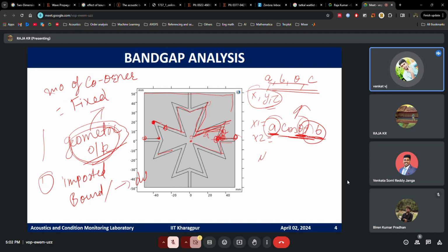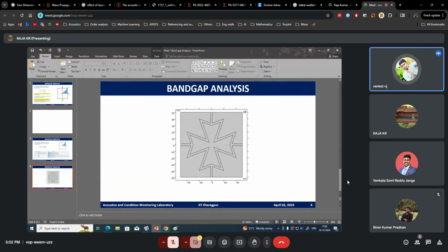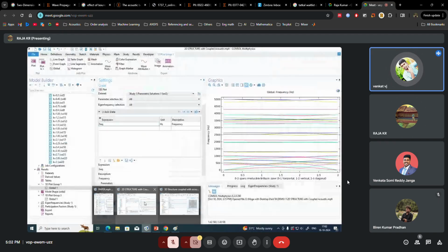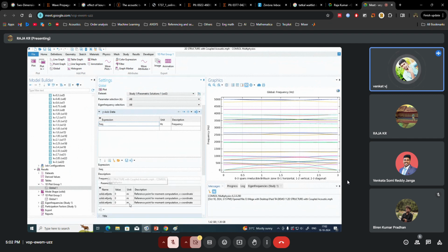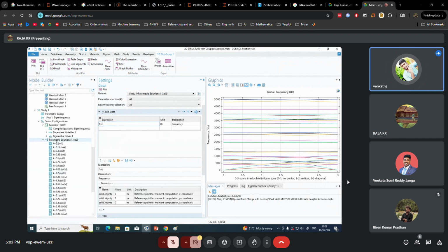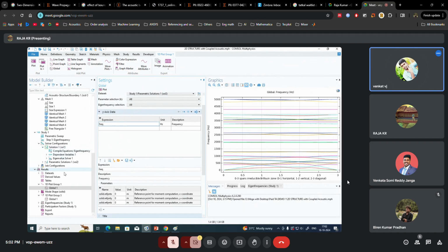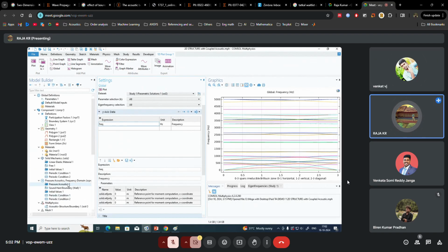If we don't do acoustic structure interaction, and just do the eigenfrequency solid mechanics study, then we don't need to draw it in the console, right? Then we can import like we did previously and just apply the periodic boundary condition. Sir, actually you don't need to make it in the console, but sometimes you will have issues selecting the boundaries.